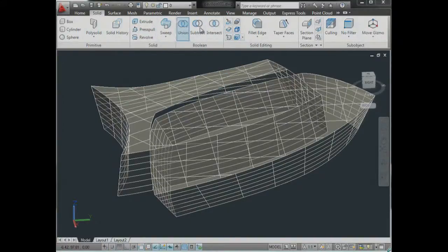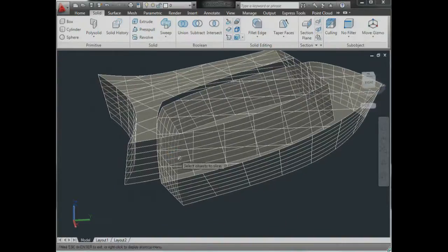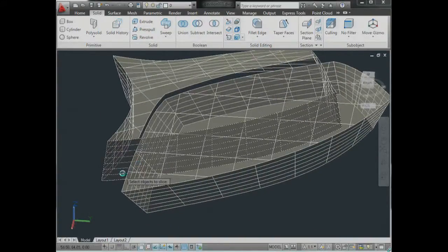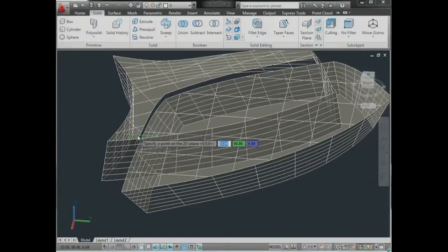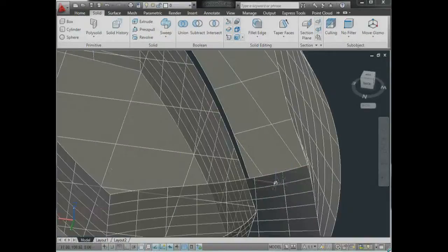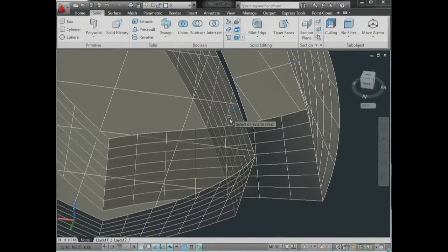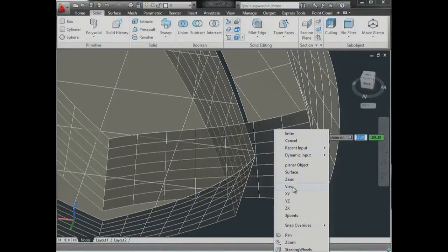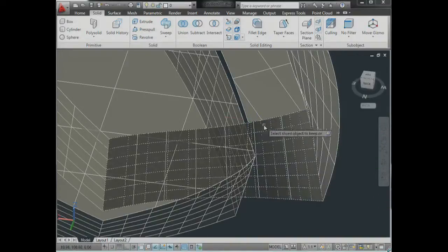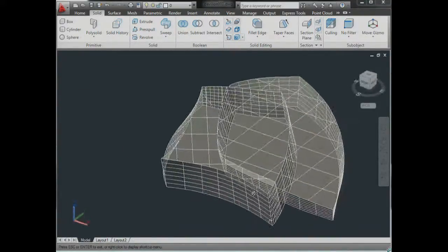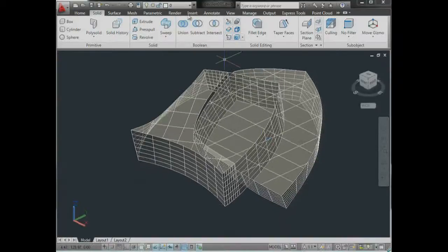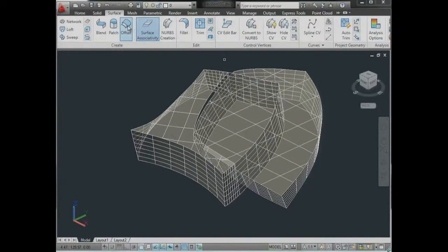Another thing I want to do now is separate the side into a slab of concrete. So I'm going to use a tool that's actually on the solid tab, but it's basically used for both surface modeling and solid modeling, in which I'm going to slice that part based on that point, and I'm going to do the same to the second part. All this will have more sense when you see the whole workflow, but basically what I'm creating is a slab which is continuous concrete going through the side into the top and back into the side, and the rest is going to be glass. So there I go, very fast. In a couple of minutes, I could have from a basic sketch all this information.